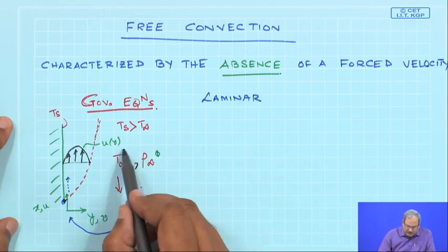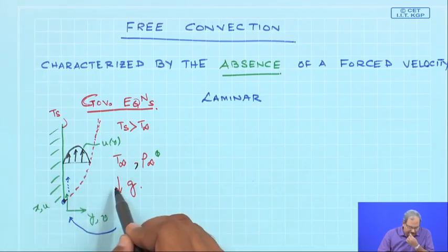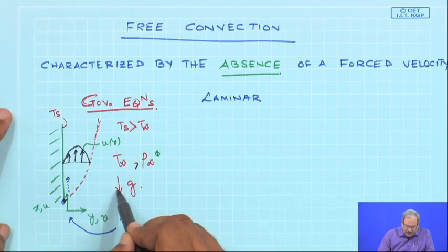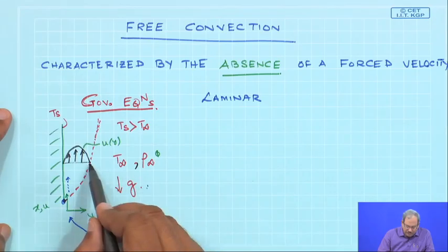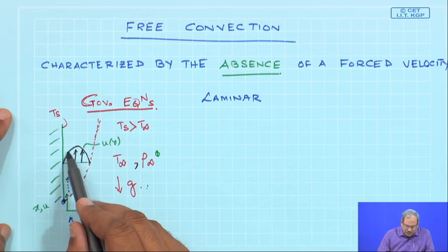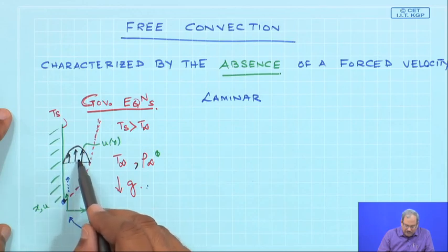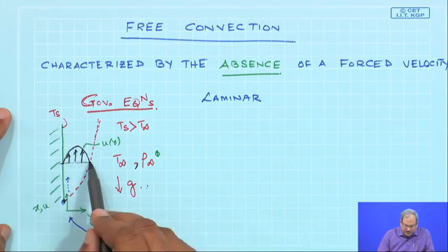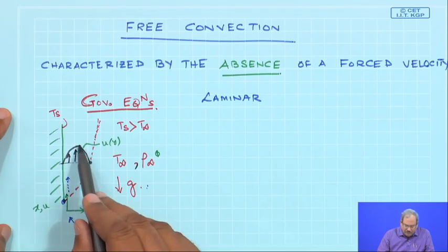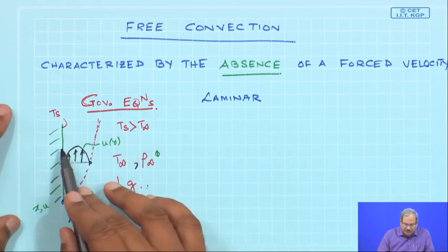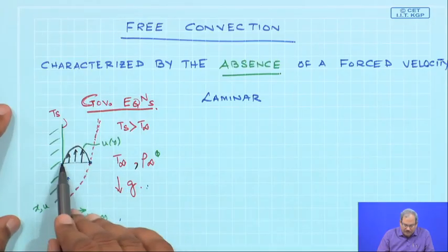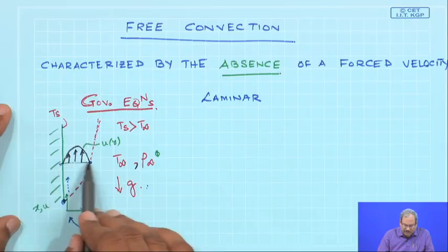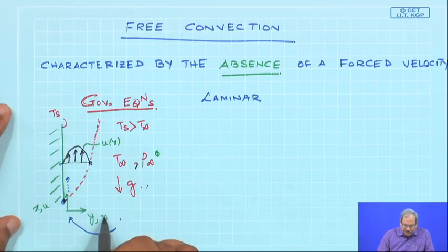And we understand that the flow outside of this thin layer is essentially stationary. So, both u and v will be 0 from this point onwards. That's why if I draw the velocity profile of the air which is rising close to the plate, due to no slip, the velocity would be 0 here, and as we understand the problem, the velocity will also be 0 over here. So, in between it will follow some sort of a profile where the maximum would lie at some point in between, but the velocities are going to be 0. The x component velocities are going to be 0 here as well as here, and we understand that v is going to be very small.